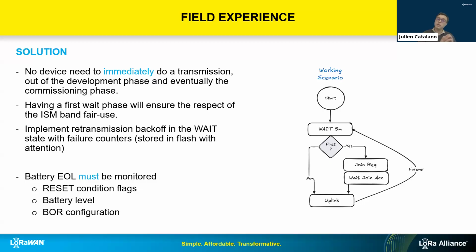We advise that you use that even if you are not mandated to by the specification. So that's one way to secure your device and to ease your deployment: to use a counter instead of a random nonce. The behavior will be the same, the security will be the same, but deploying and not having to remember all those random nonces will be much easier on the network side and on the device side as well. That's really what we want to emphasize here today: the recommendation in the technical documentation you can download on the website adds more robustness to what you could do when you develop a device.